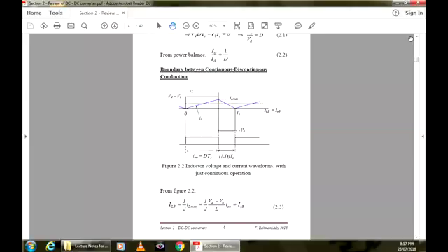So in this operating condition, what is the value of IL max? ILB equals half of IL max, and that is half of (Vd minus V0) divided by L, which is the rate at which current rises, times the turn-on time, which is dTs. So you get this value for a given d, which is I0b. So the current waveform for operation at the boundary has to be like this, and if we know Vd and V0, then I0b can be found.